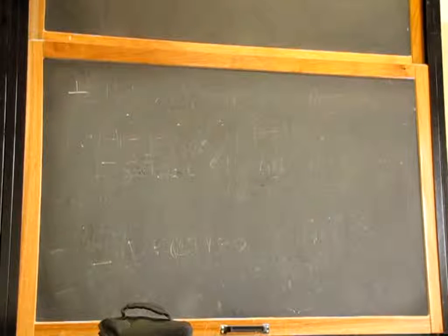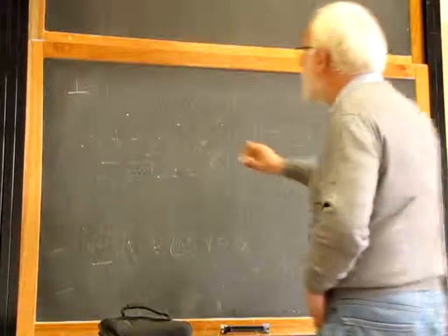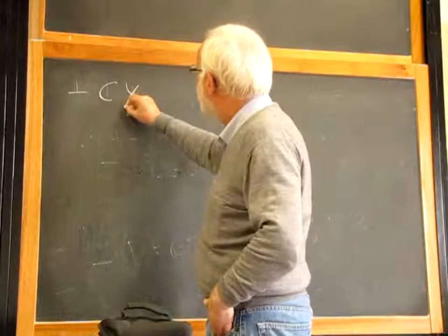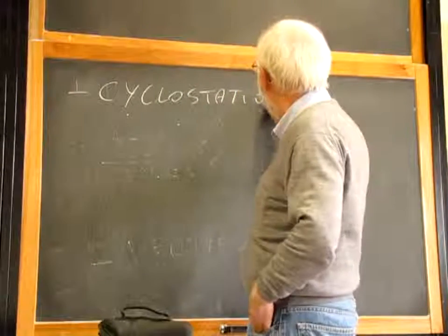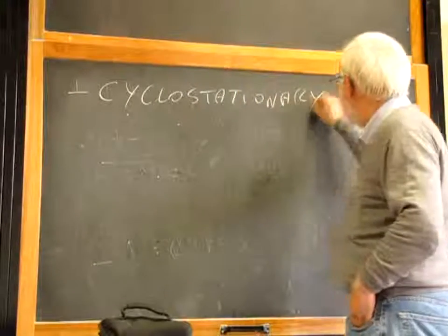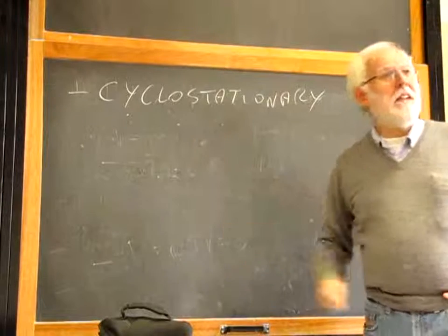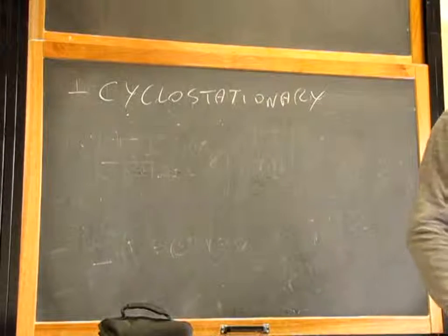There is no steady state in a switch mode converter, because your switch opens and closes continuously, periodically. So there is a sort of steady state that is not freezing the switch in one position. That is called cyclostationary condition. We will make at the beginning a cyclostationary analysis.